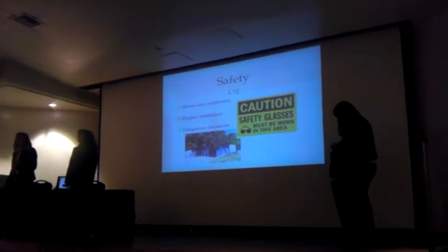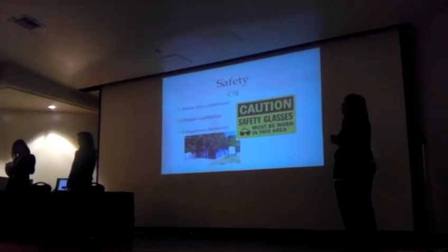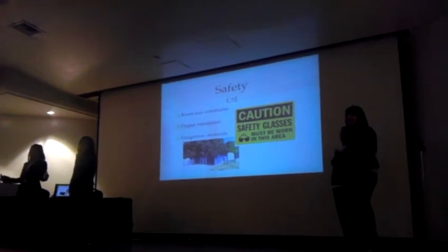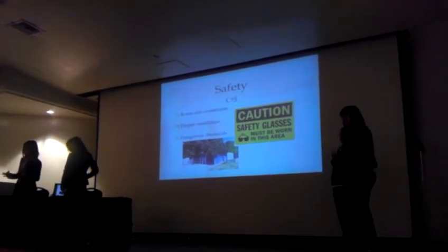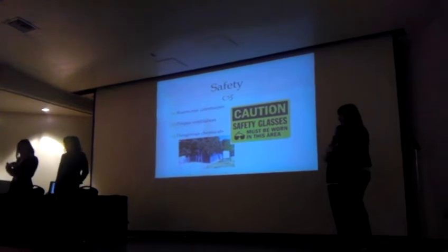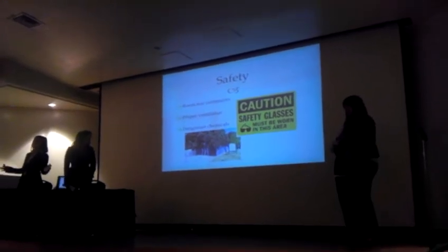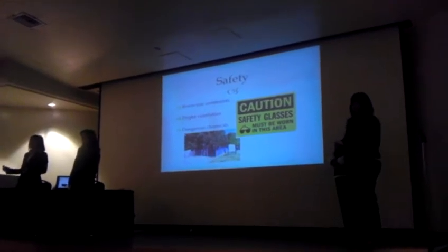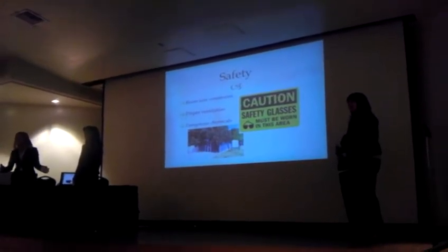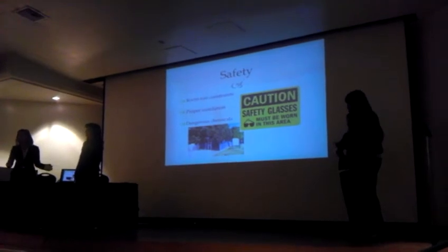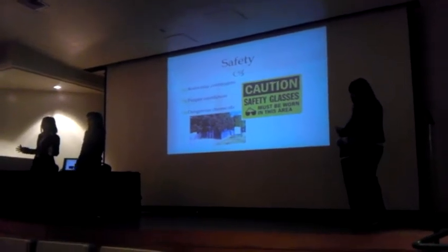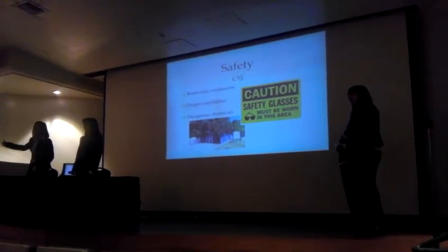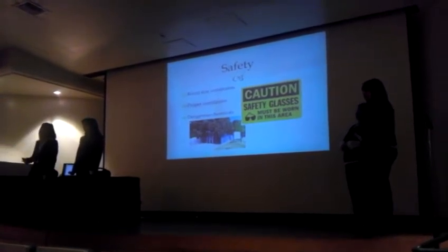All right, so safety. We'd like to thank Mike Christensen for bringing in the safety inspectors to take a look at our system before running any biodiesel, because it can get pretty dangerous. It turns out that the room is actually too small for our system, and we don't meet any of the fire standard codes. There has to be a certain amount of distance away from the wall to your actual system to ensure that if anything does happen to someone operating, they have an ample amount of time to get out and exit the building, which we do not have because the room is too small.